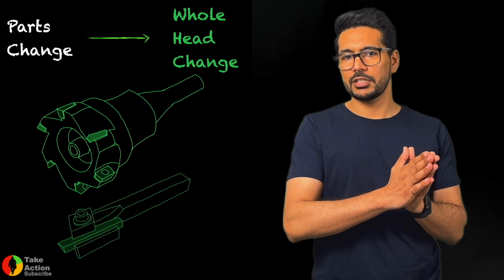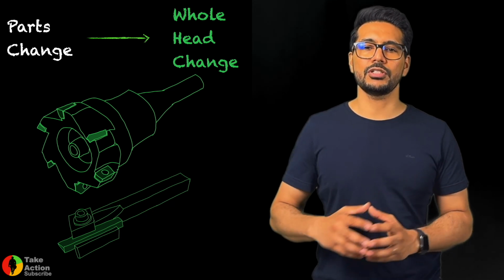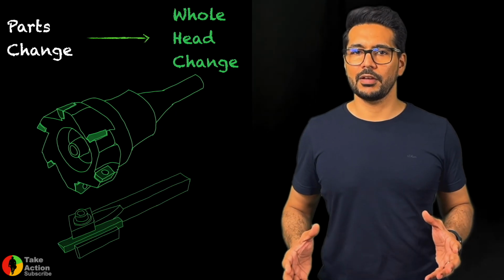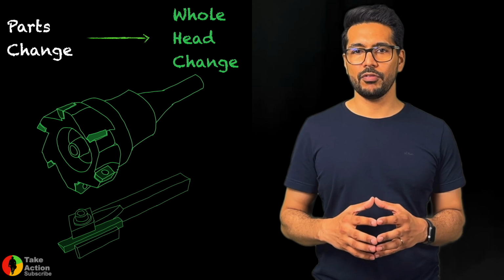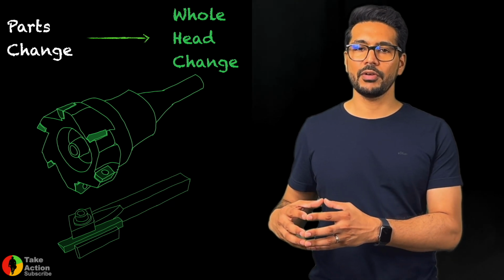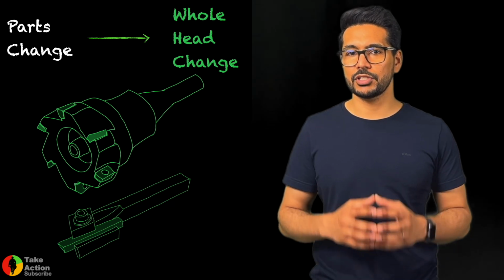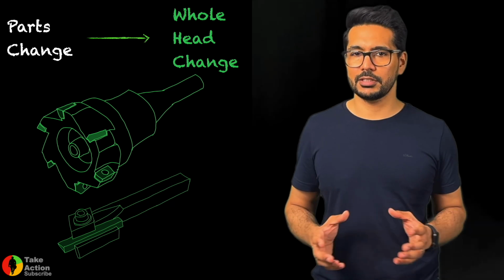In case we take the complete head out and replace it with a new head, which is anyway in the company as a spare part, then we are much quicker, and we have offline a lot of time to check, inspect and do very good quality setting, and the machine downtime for this activity can be drastically reduced.